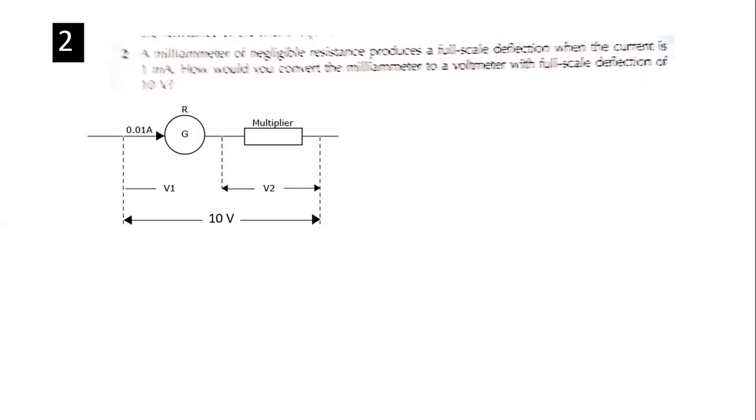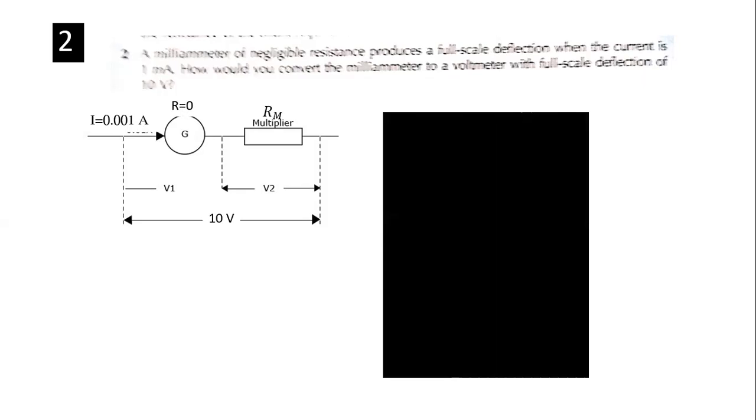Right? Just remember, this one voltmeter is galvanometer and multiplier. Then write down all your values. What is given? Then go and calculate. In this case, R equals 10,000. Equivalent RM is V over I. You are told that your current is the same.